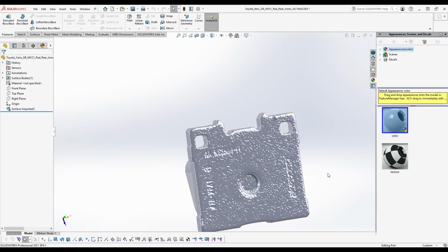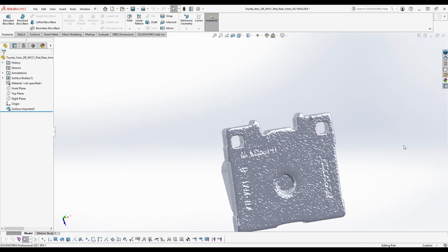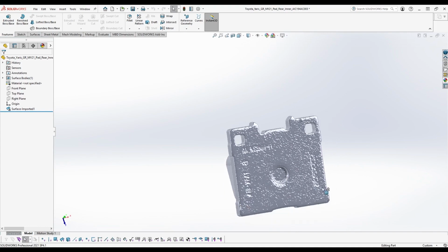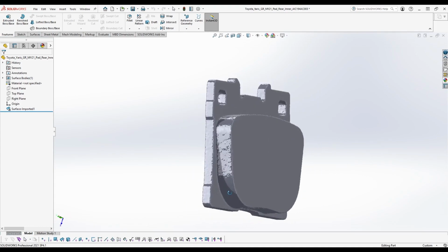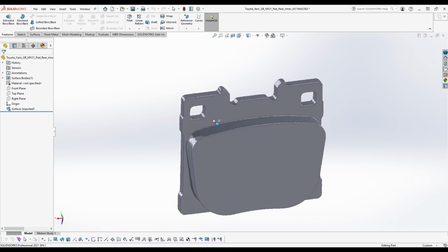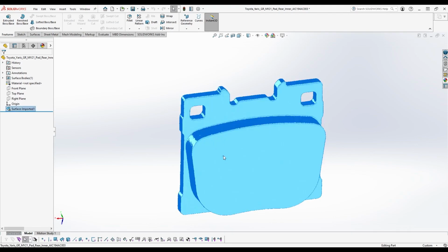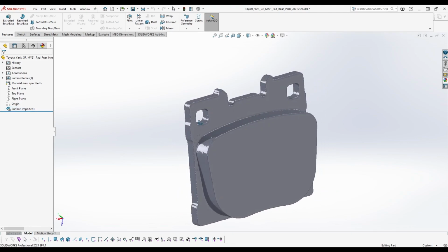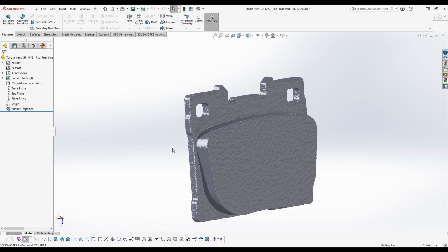Now, what's wrong with STLs? Well, some CAD programs are fantastic at working with STLs. But the majority of our customers use SolidWorks or something of a similar level, and they have less functionality with these STLs, and historically they've had a bad reputation for how they handle them. The issue is always that you can't click on it, you can't do anything with it, it's just a big graphic. That is kind of true to a degree, but there is certainly some interaction you can do with the STLs, and I'll show you how.